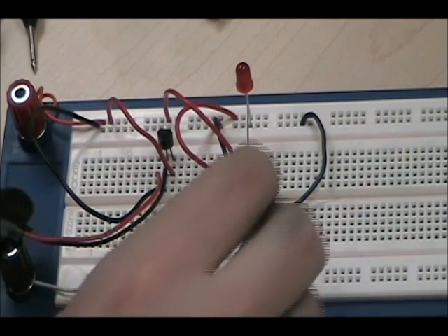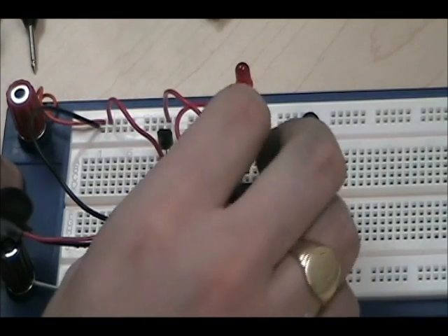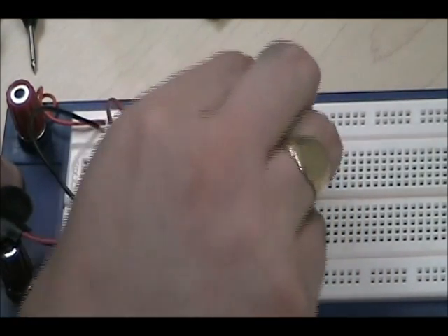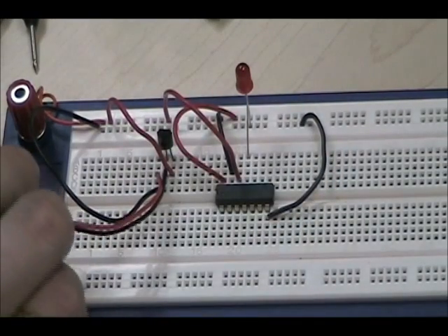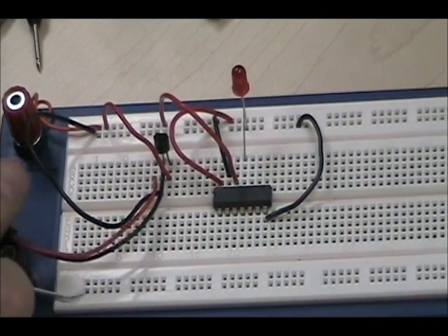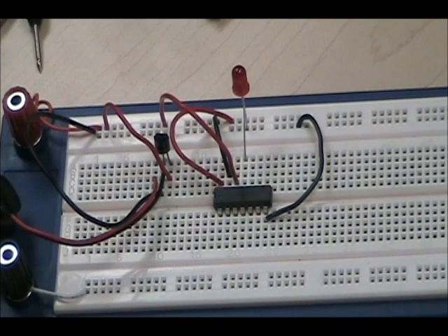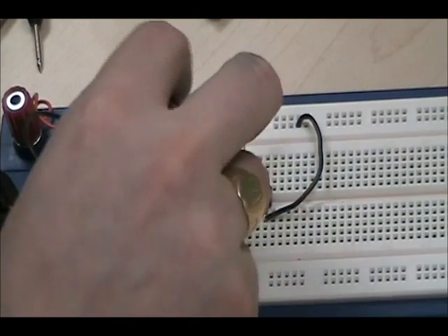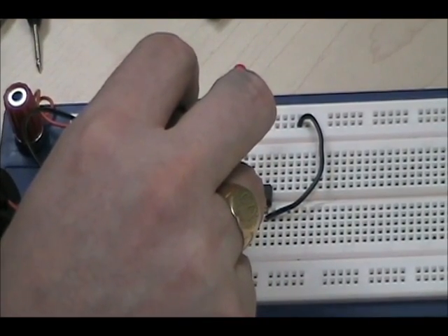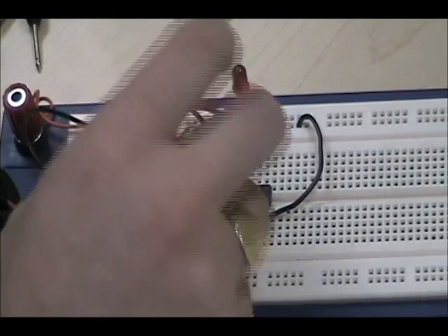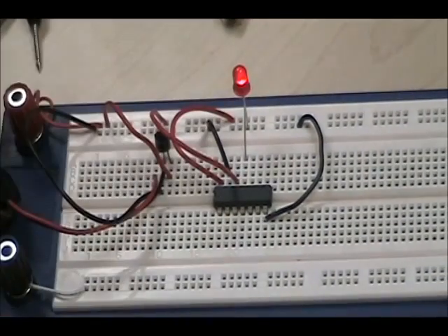So let's power it up. Let's start with both of the inputs at high logic. So it should stay off when we power it on. Okay. So the chip is properly powered, properly grounded. Both inputs are at high. So since it's an inversion of the output of an AND gate, the output is low. We bring any of the inputs to ground, the output goes on. Any of them, either or both, it doesn't matter. If we bring either one of the inputs to ground, the output goes on.